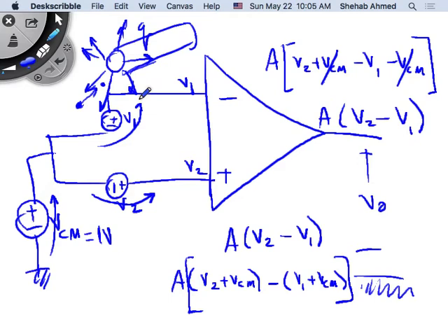So now let's say you have this sensor measurement, flow meter measurement system with two wires coming out. You don't know what's around. Sometimes you will measure something weird, something with noise, for example, or an offset, and you will be confused about what's going on. Some signal has coupled to the wire due to a magnetic field or electric field.